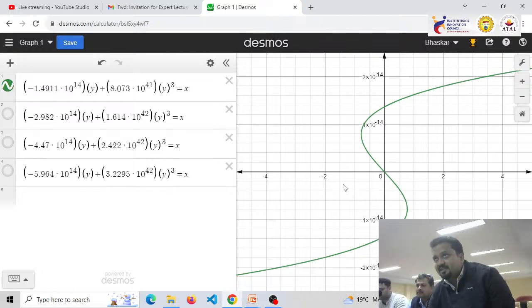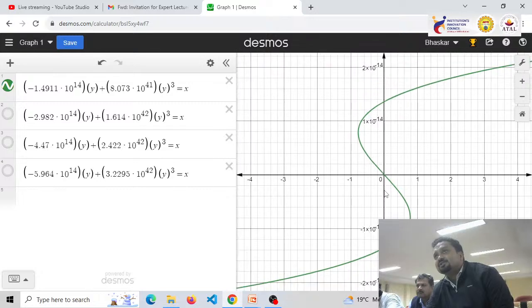Now as you can see, I will zoom it a little bit. So you can see in this particular region, the gradient or slope of this particular characteristic is negative. So as I am increasing the voltage, my charge is decreasing. So that shows me the presence of negative capacitance in my ferroelectric oxide, because here I am increasing the voltage and the charge is decreasing. So this characteristic with the green line is for TFE equals 30 nanometer.